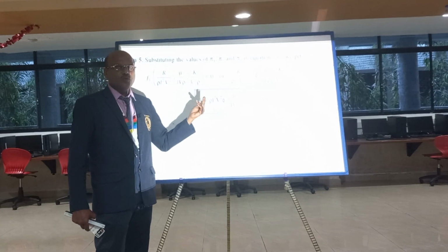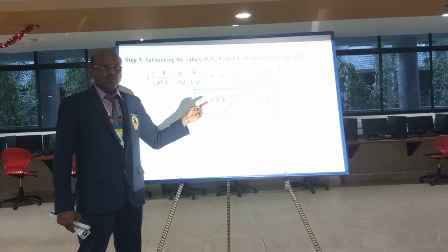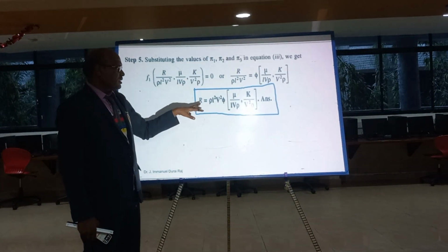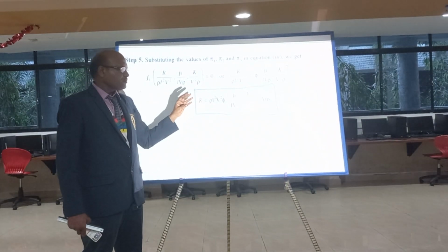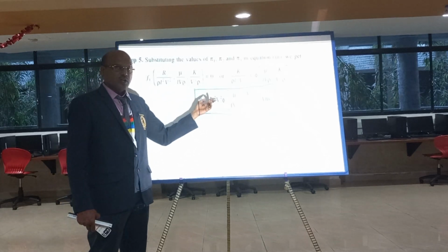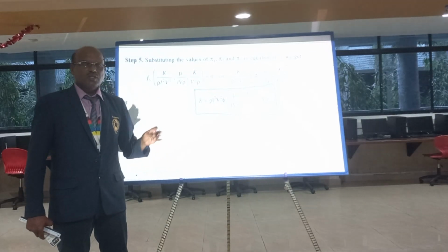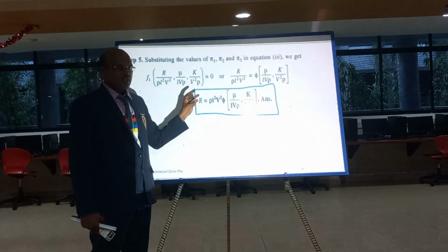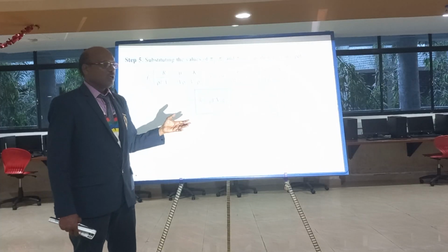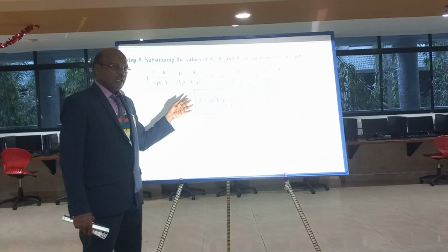For all the equations you frame through any research, you have to solve only through this method. It is what you have to find out. So it is very easy to solve, even with 6 parameters. Through Rayleigh's method it is really difficult to solve like this. Even if you have n number of parameters, you can easily solve the relation between the parameters. So through the Buckingham pi theorem, I can solve the dimensional analysis more easily than by Rayleigh's method.